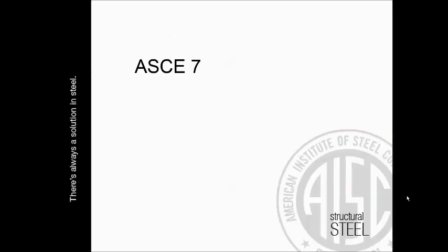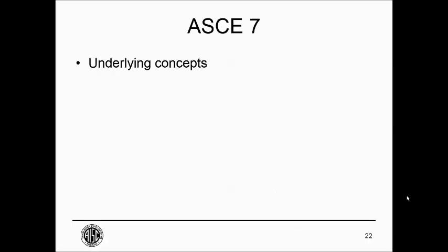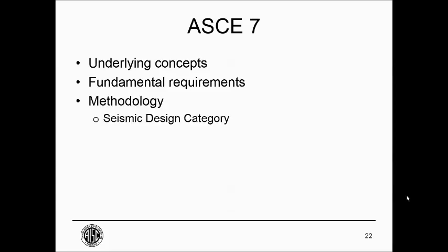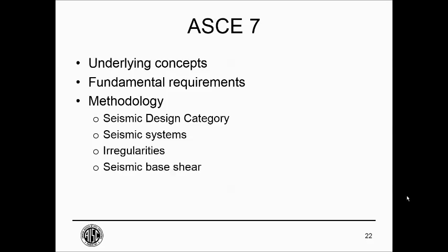All right, so let's start with ASCE 7. We'll discuss the underlying concepts, some of the fundamental requirements, the methods used, including determination of seismic design category, selection of seismic systems, handling of irregularity, and determination of seismic base shear, selection of analysis method, and diaphragm requirements.